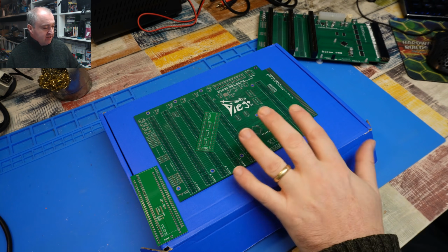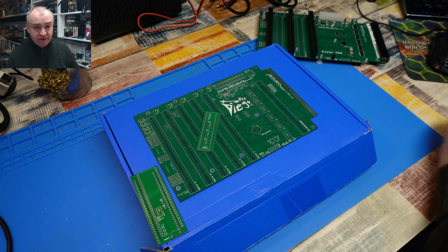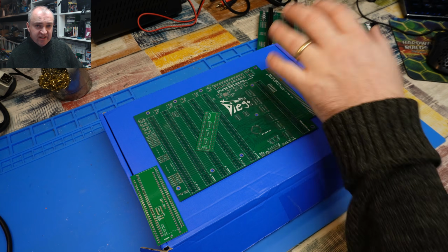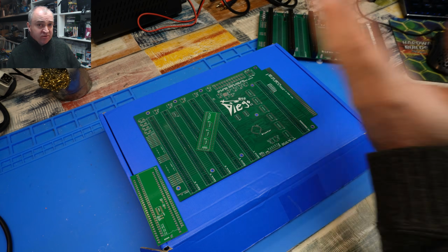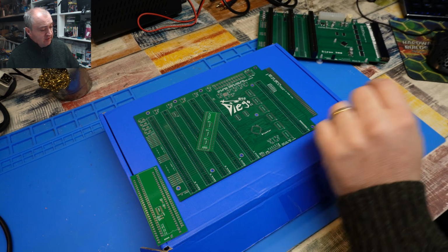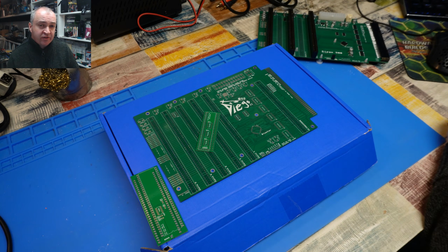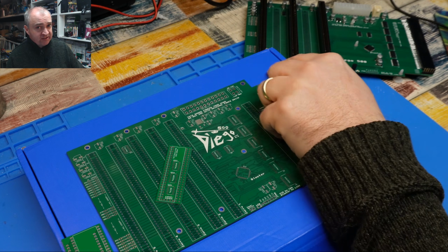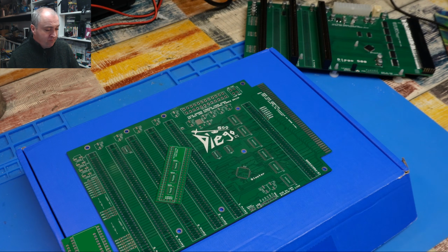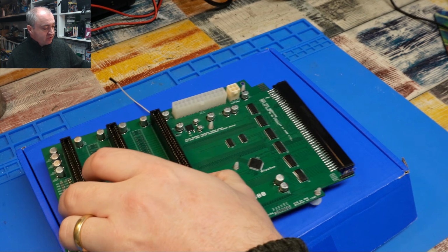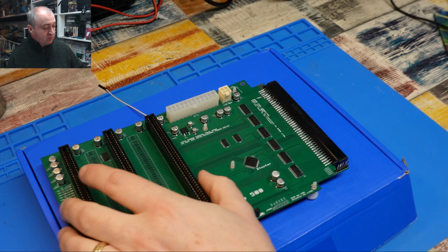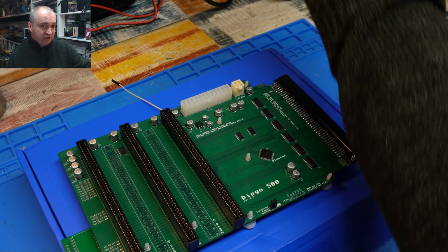So that's the only stipulation I am making with my board here. You must power it using an ATX power supply. Even a Pico ATX power supply should be enough. And you must run a wire from there to the back of the A500. Now the power rails are connected at the edge slot. And I'll be honest with you, testing with this one, it does work if you just plug that in with the ATX without the loopback cable.